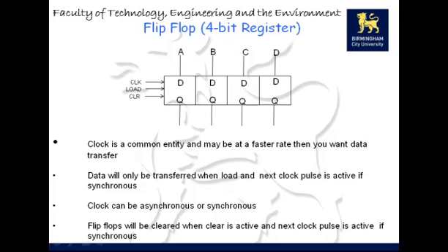But before we do, let's have a quick recap on what we covered in part 1 of the presentation. We looked at registers, not shift registers, but registers. And registers are used to store bits of binary data. Here we've got 4 D-type flip-flops. We can store 4 binary values. Hence, it's a 4-bit register. Now, clock is assumed to be a common entity to the whole circuit, where this is just one particular element of a complete circuit. So clock is a common entity. However, load and clear lines are specific to these registers.